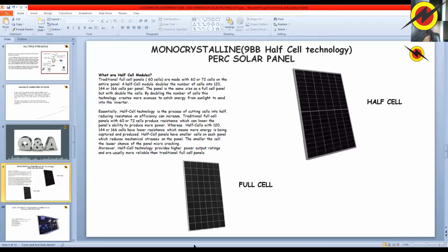You want to make sure it's in agreement with every other component which is going to make your solar power system. You look at the VDC of your charge controller, also the VDC of your inverter. So provided that is in line, you can use it with other panels, provided it works for the purpose you intend to use it for.